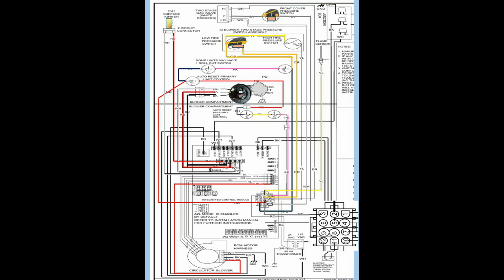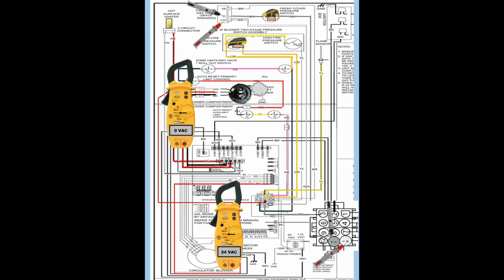If the gas valve doesn't open, is there voltage at low fire and common on the gas valve? 24 volts at pins 10 and 11 in the 12-pin connector. We see there, we're looking for 24 volts, and we're looking for it here at our pins 10 and 11. But we need to know, do we have voltage there?